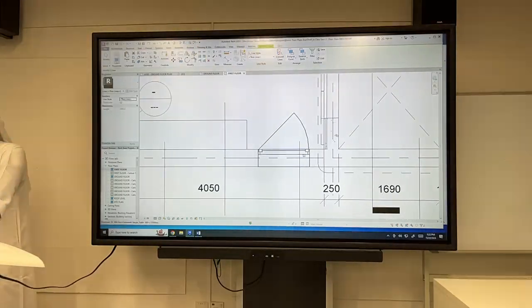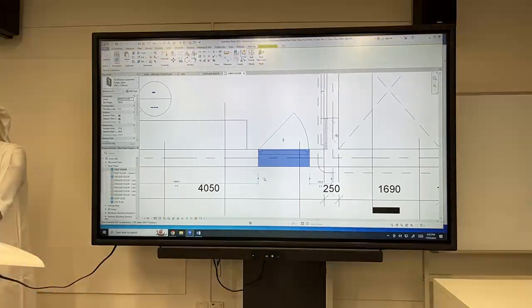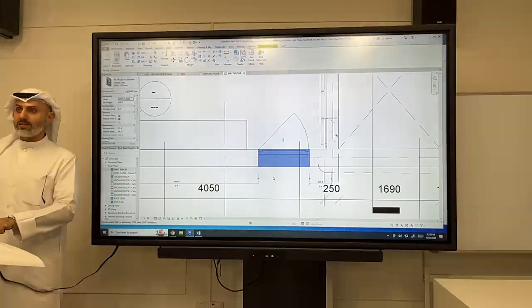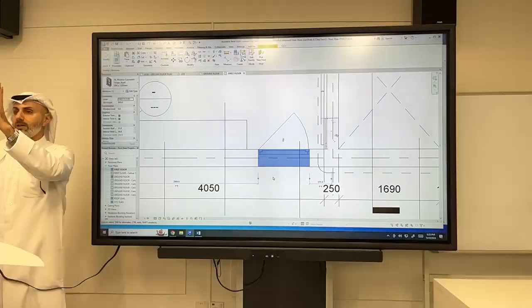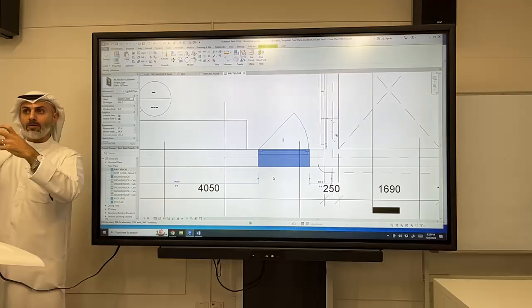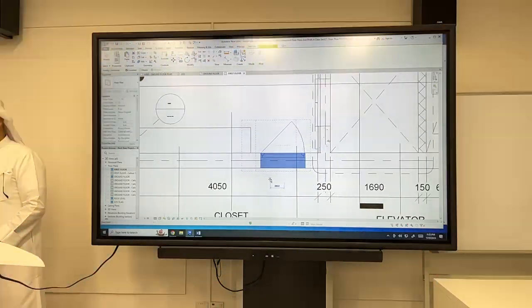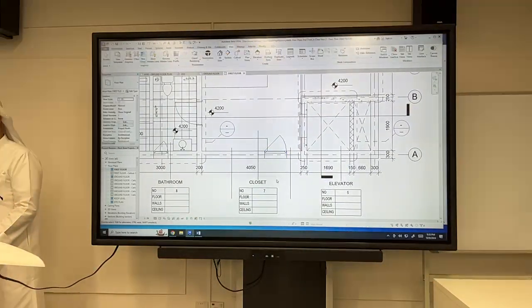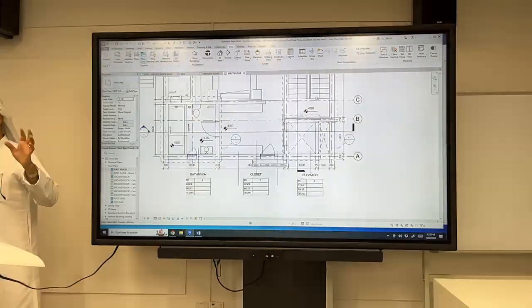If you have a window where you want to cut the wall, move the window. Do not keep the window, because it's not impossible to do that, but it complicates things. If you have brick mortar and then suddenly a window in the middle of this material and that material, it complicates the construction. So you can move it or change the size. And you do the split the same way. But don't do it now, because we have time.